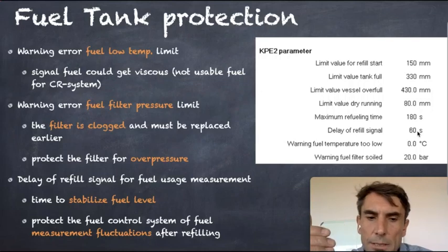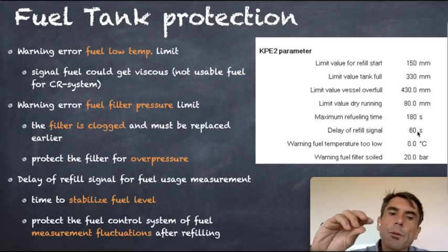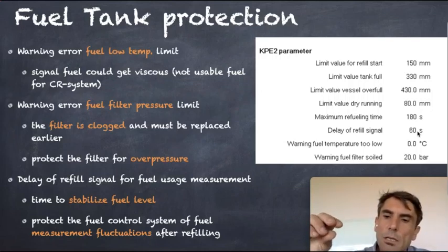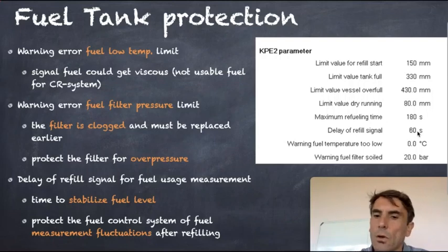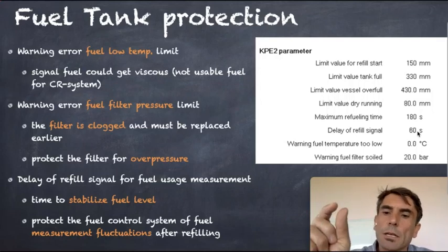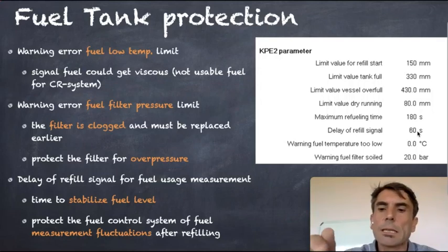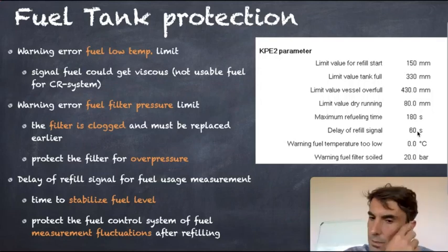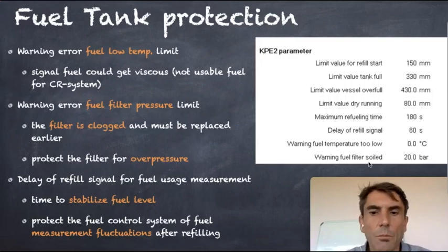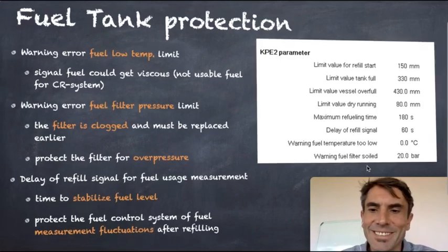So we need the stability, otherwise if the measurement fluctuates too strongly, it will have a direct impact on the pulse width of injection of the injectors, and that could damage the injectors. Okay, but we will go into that deeper. Don't worry.